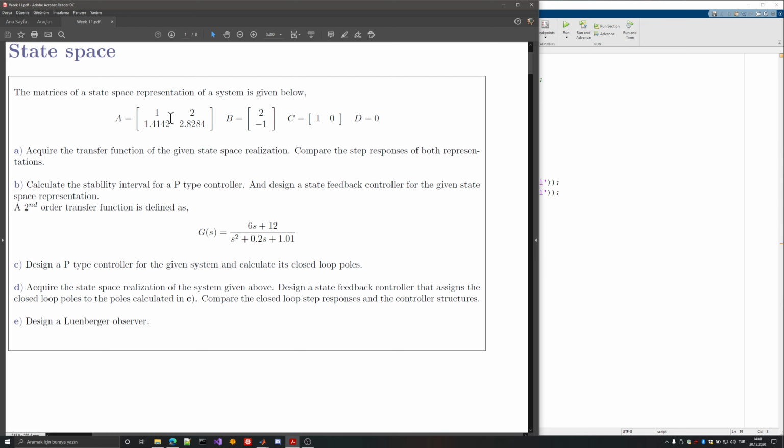Now, this is the reason why we may need some observers. An observer means that you know the mathematical model of the system, and maybe you can reduce this measurement, and maybe you can reduce this sensor need here, so that you just observe the output, or you're measuring again only the output, but this time you add a structure that will, in quotes, measure the output and estimate the states for you.